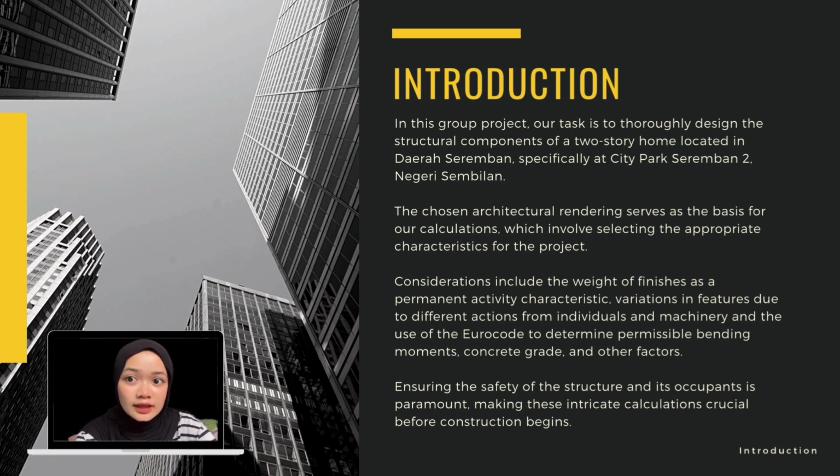The chosen architectural rendering serves as the basis for our calculation, which involves selecting the appropriate characteristics for the project. Our considerations include the weight of finishes as a permanent action characteristic, variation in actions due to individuals and machinery, and the use of the Eurocode to determine permissible bending moment, concrete grade, and other factors. We also ensure the safety of the structure and its occupants is paramount, making these integrated calculations crucial before